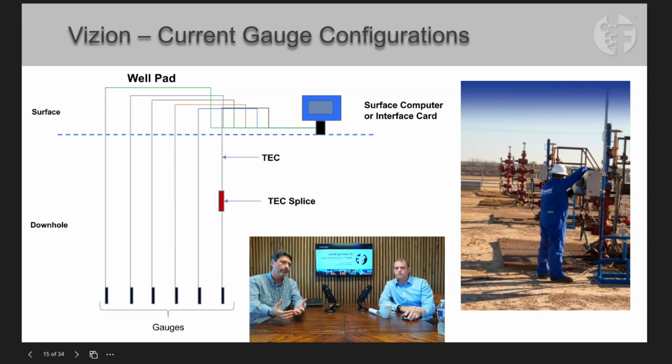And that information is pulled into the computer's memory, and then is available there for the SCADA from the customer side to pull that information to that server or to that system. Okay. And what is the power requirements for one of these gauges? 24 volts. 24 volt is the DC power system.